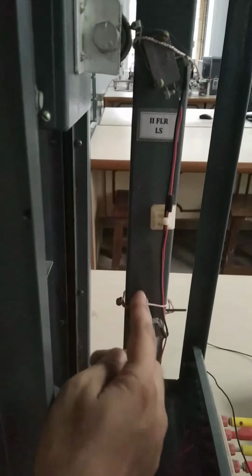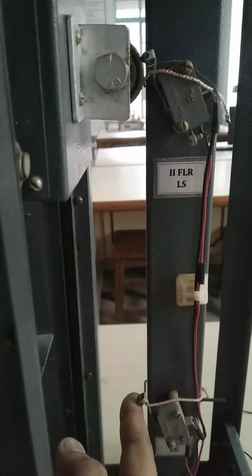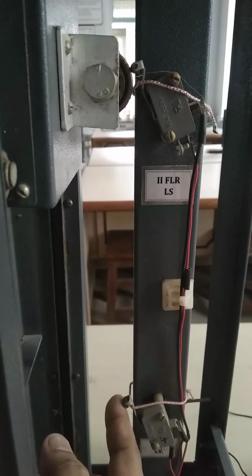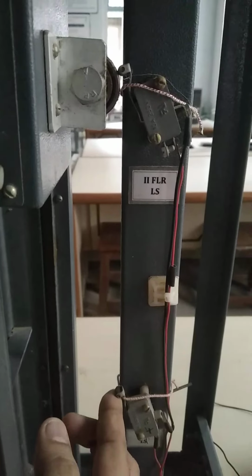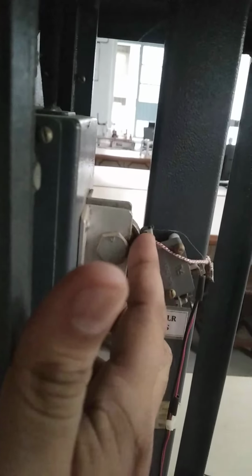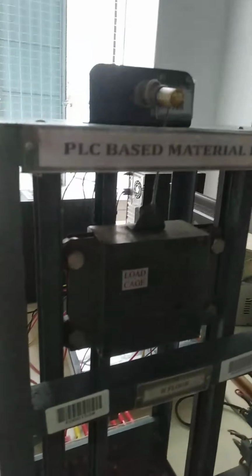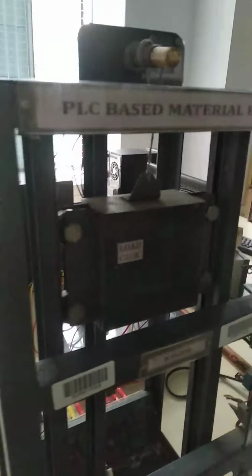In order to detect the presence of the hoist, 3 limit switches are provided exactly at each floor. See, this is a limit switch. This is a limit switch. Similarly, this is a limit switch. A limit switch is a mechanically actuated switch. That is, when an object slides over the limit switch, the contact will be closed, just like a switch getting closed. So when the hoist slides over the limit switch, it will get activated. Therefore, there are 6 inputs in the setup: 3 inputs from the push buttons and 3 inputs from the limit switches. And as explained in the program, we have 4 outputs to change the direction of the polarity of the motor, that is to move up and down.